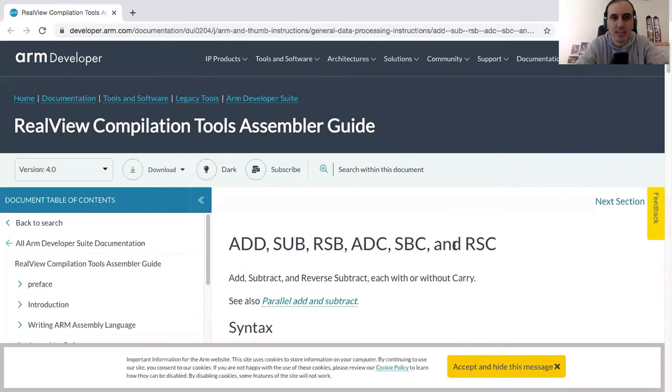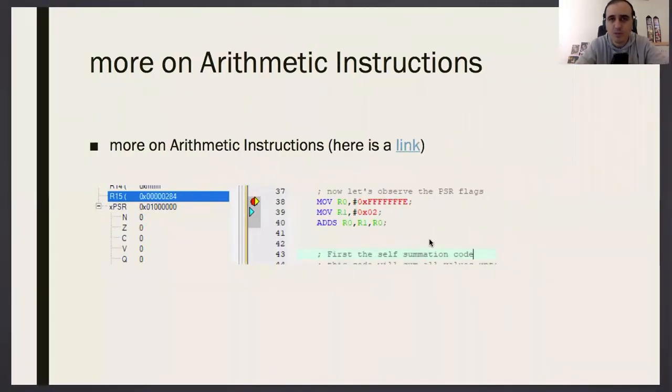You can find any instruction here. So guys, I'm doing a test here. I'm moving a value to R0. Actually, I'm doing something strange. I'm moving a 32-bit value to R0, and it's not going to move. It's going to take only these two. Okay? Then I'm going to do another move. Then I'm going to do an add instruction and test. Okay?